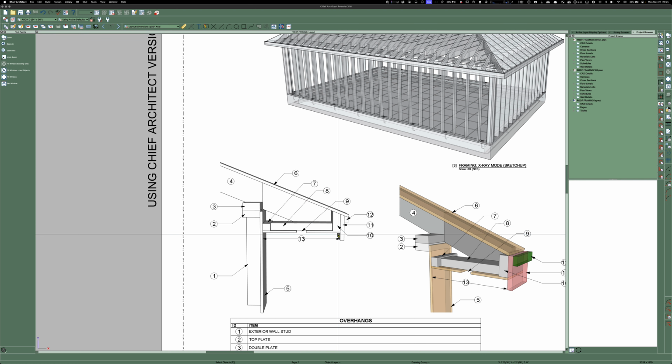And the only time you really get into trouble with overhangs is if your overhang is going into like a setback area or some kind of area where it specifically says from the permit office that you cannot extend into that area. And then you'll figure out how to make that work. Otherwise, you go with whatever's delivered on site to use as soffit. And the other question I had was when people get adamant about, oh no, the overhang is always to the outside of fascia.